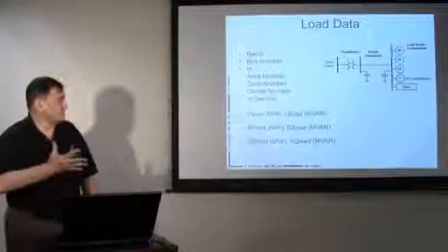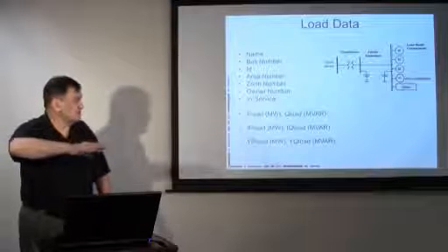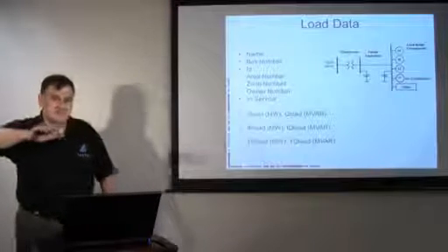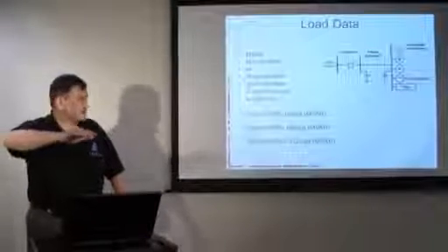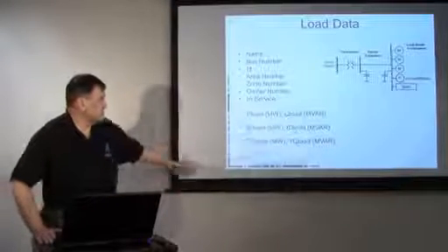And the load can be 3 types. It can be a megawatt, megavar value that is constant no matter what happens to the voltage. It can be a value which is a constant current. Well, that means that as the voltage drops, the actual load will drop linearly because the current is constant, power is voltage times current, and that gives us a linear dependence.